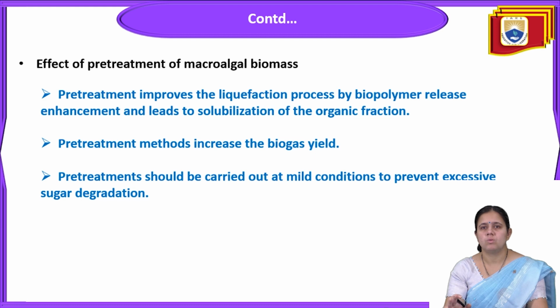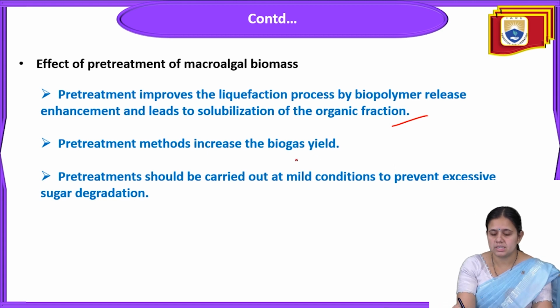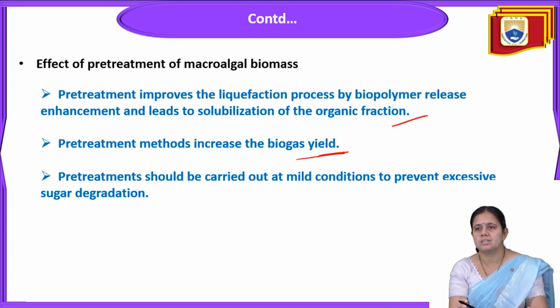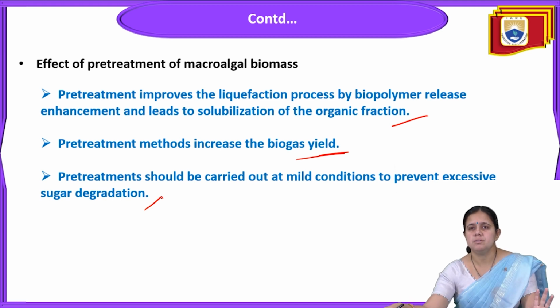So why is this pre-treatment required for the microalgal biomass? What are the effects of this pre-treatment on the microalgal biomass? Pre-treatment improves the liquefaction process by biopolymer release enhancement and leads to solubilization of the organic fraction. Pre-treatment methods increase the biogas yield, and the pre-treatment should be carried out at a mild condition to prevent excessive sugar degradation. So three important points are required for the pre-treatment of microalgal biomass.